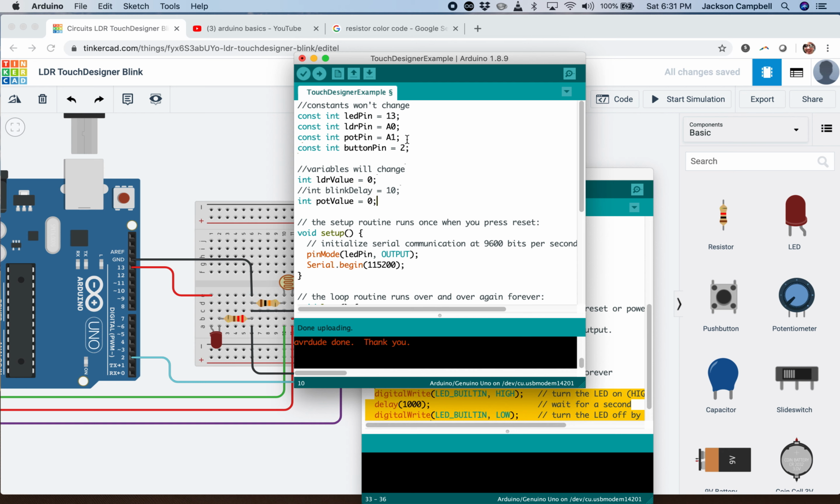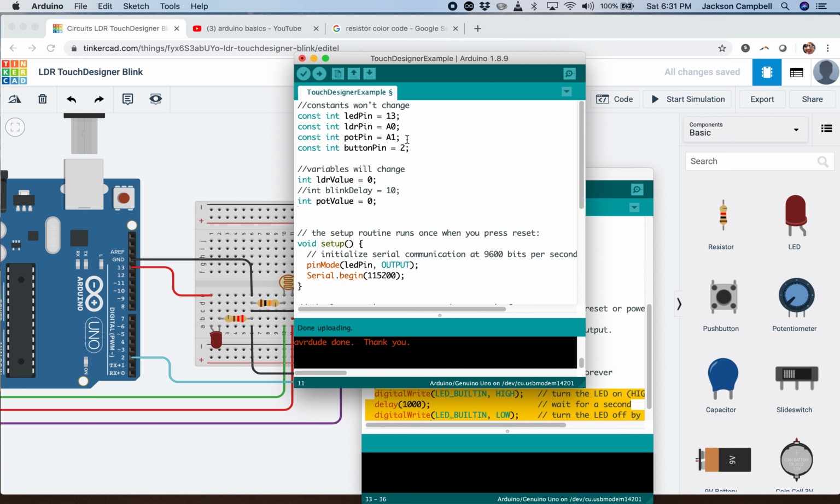Okay, then we're going to have our variable here called int buttonState, right? Because it's going to have state changes between 0 and 1. And because its default value is high or 1, we're going to make its initial state 1 because that's when you're not hitting the button. All right, so buttonState equals 1.